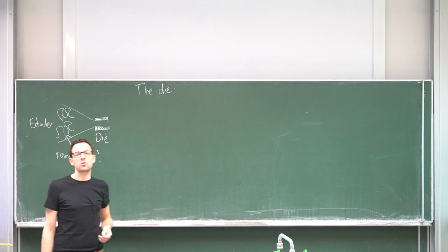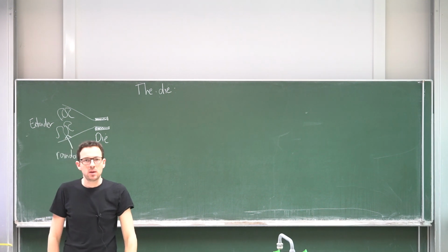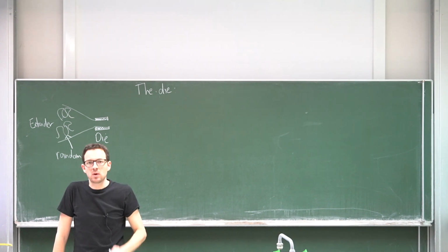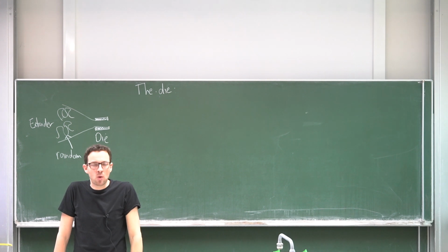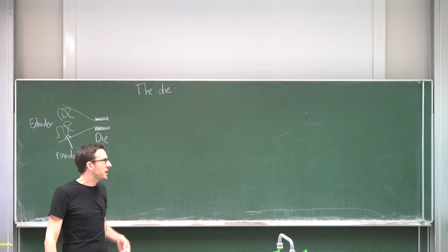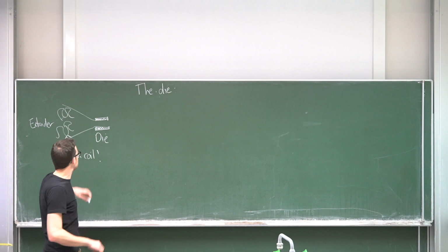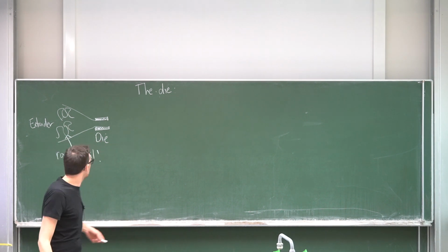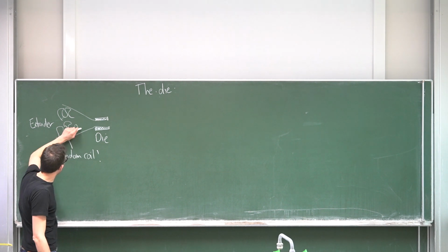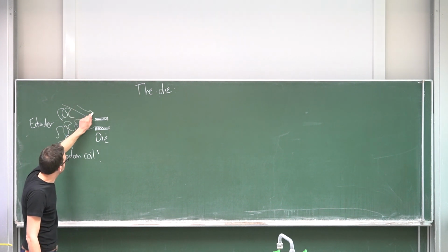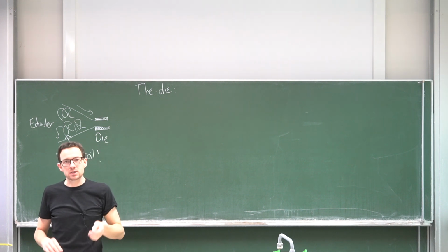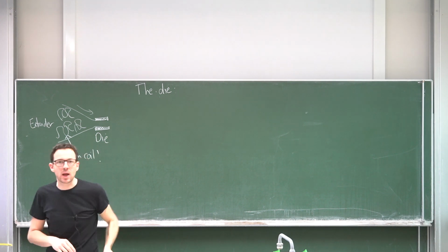And why do they like to be in the random coil? Think back to one of the last lectures, or a few lectures back. The reason is because this is entropically favored. The maximum number of microstates is achieved for this random coil configuration. So now this random coil polymer approaches the die, and because the die is very thin, it is squeezed at high pressures through the die.